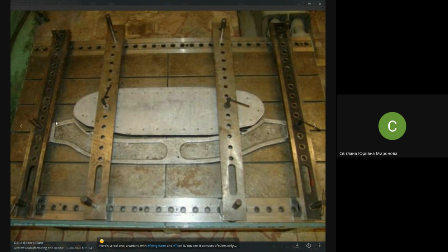And on the locator you might see that it has a contour which is measured from this base axis, and mounting holes here and there which are measured from the same axis. While mounting the jig, the mounting hole will be your axis for measuring next, like you are transferring the axis from the base one, from the plane of symmetry of the fuselage or the constructing plane of the wing, onto the axis of the mounting hole.